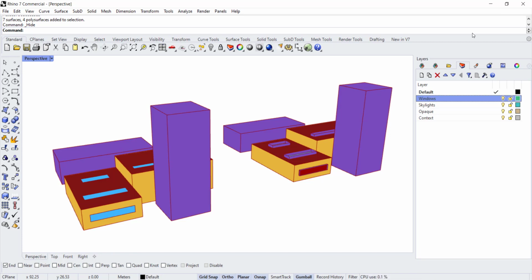In this video, we're going to review two ways to add a grid of test points for daylight modeling. Test points are required because the Radiance engine will use backwards ray tracing from each sensor point that you add to your model to find the sun and give you an indication of how much daylight can actually reach that point, that sensor grid that you set up.